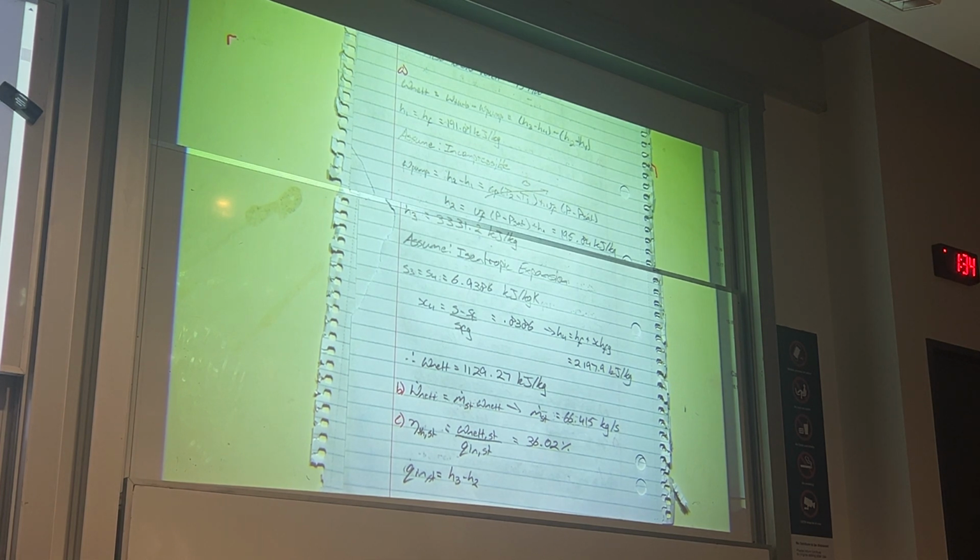So pretty much we want to estimate the temperature of the air in the gas turbine exhaust, basically we want to find T9, and then we want to find this temperature pinch point, which is pretty much the temperature when you begin to boil the water.